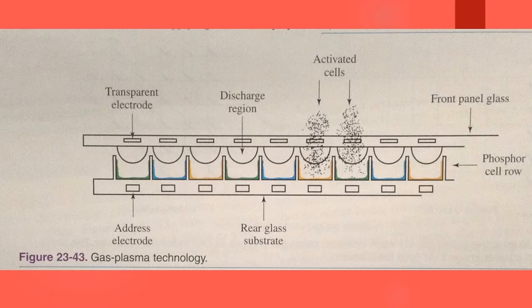A voltage applied to the crystal causes the crystal to warp and in turn determine the amount of polarized light passing through the display screen. The LCD is classified according to the electronic circuitry and method used to apply light to the display's surface. There are two categories of LCD, active and passive. Passive displays are often more affordable than active displays because they require fewer transistors and are less complex. Active matrix displays are costly because they use one or more transistors at every pixel.